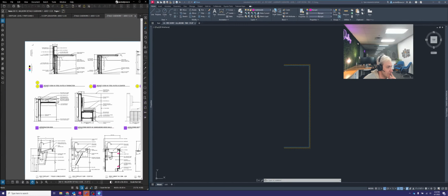One other thing I can do as well is if I'm not too sure and I don't know where to look for that, I can also try to scale this too. So to do that, again, you're going to go to the view title on the bottom left-hand side of your drawing. And you're going to look for this guy here. That's your scale right there. Looks like 1/8 equals a foot scale is the scale they used to draw this. So we're going to go over to this ruler measurements icon in Bluebeam, we're going to go over to presets, and then we're going to set this to be the exact number that's here. So 1/8 equals a foot.